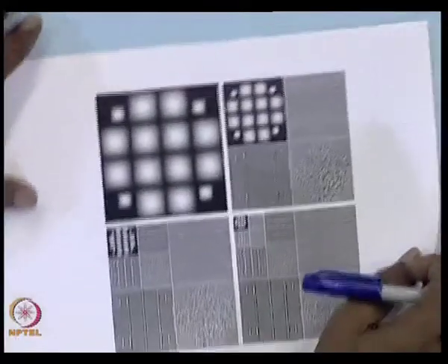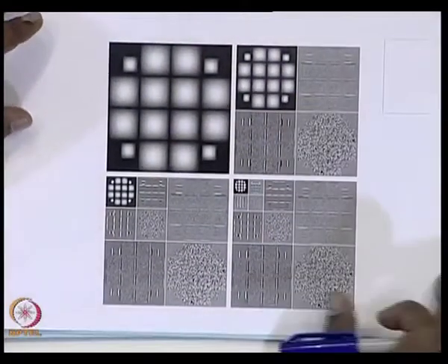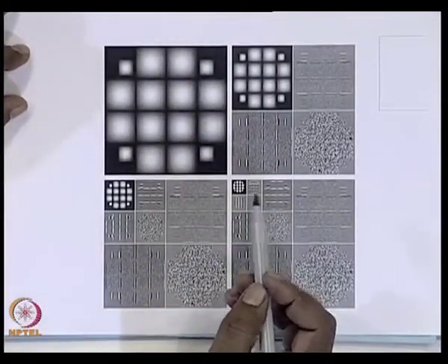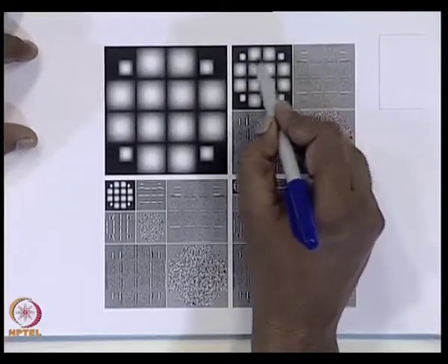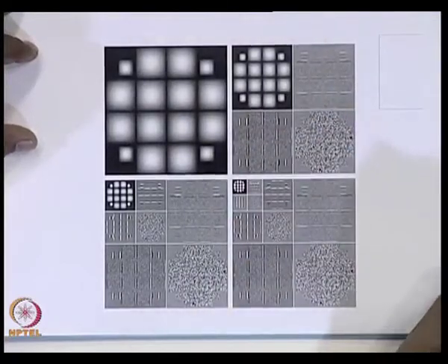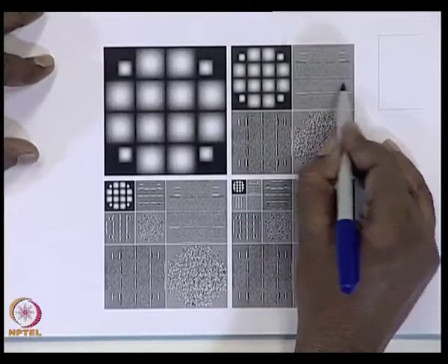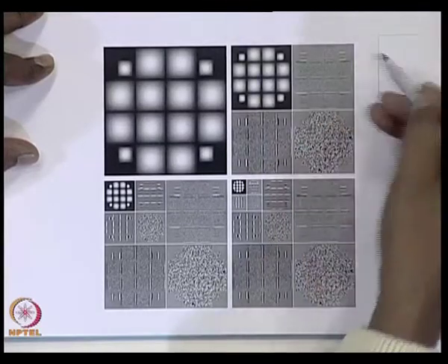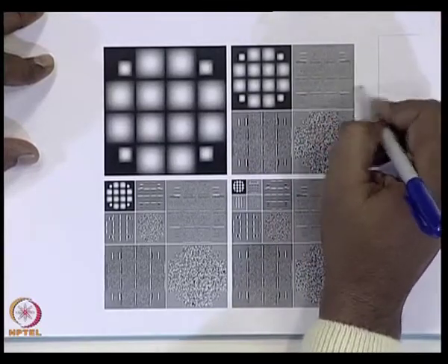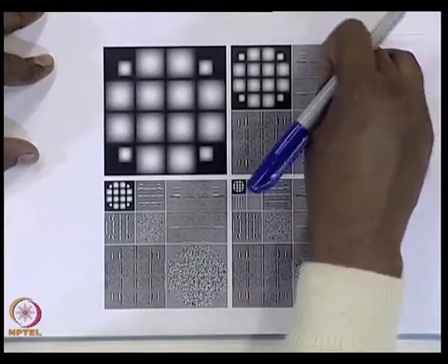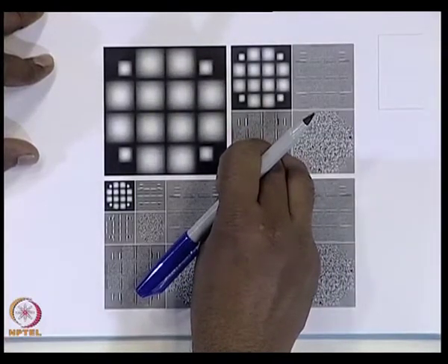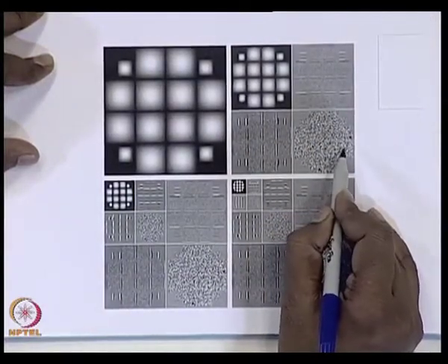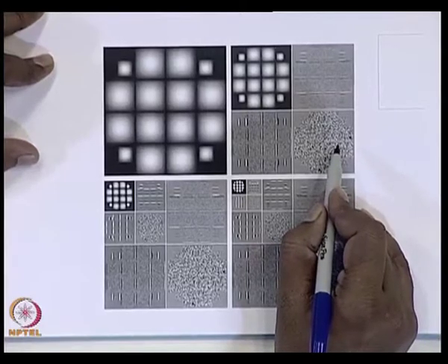So, this is an image. Okay. Suppose this is my original image. After the first level of decomposition, I get this lower resolution version of the same image. Over here, I have all the horizontal edges. Here the combination was different: high pass filtered horizontal, low pass filtered vertical. It does not matter whether I put that subband here or here. Okay, it is simply positioning. And this is the HH subband. So, this is what I have after the first level of decomposition.